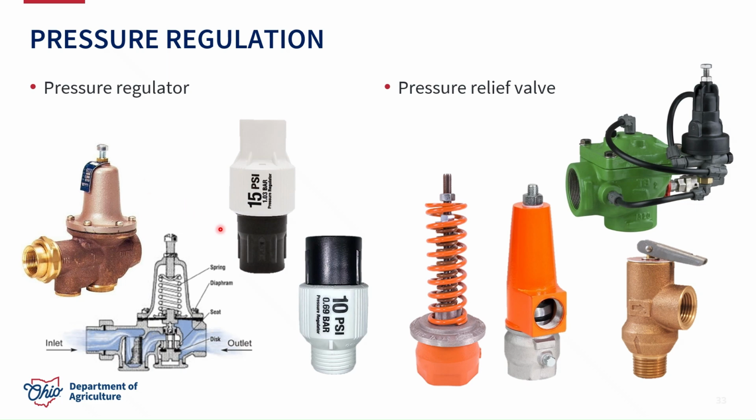As we get into our manifold hose and tubing, right, as we discussed earlier, that microsystem typically operates at a pretty low pressure. So you're thinking using something like these inline pressure regulators set to 10 psi, 15, 20, as low as 8 psi. And those are then going to protect all the lateral lines downstream and evenly distribute the water per the microirrigation design.